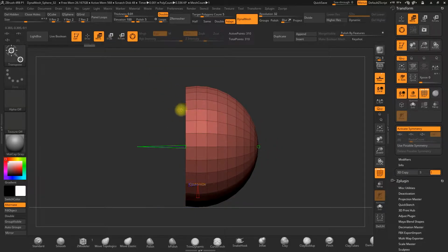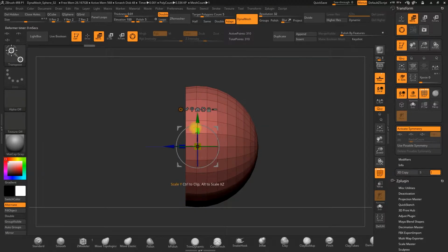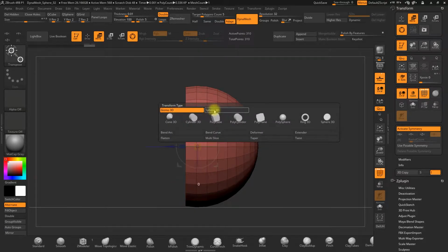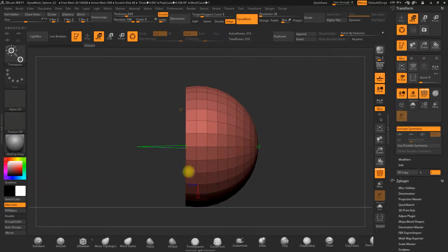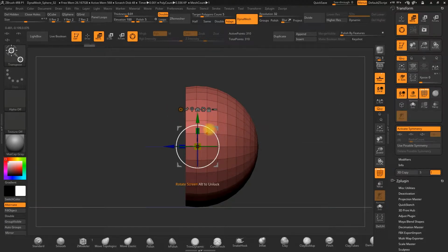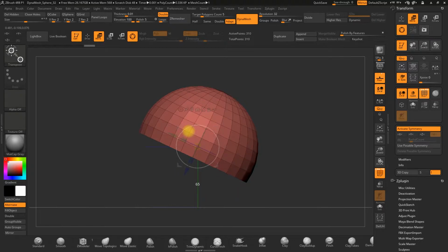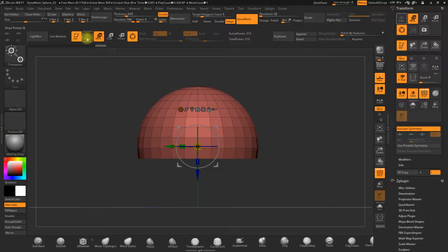Take this, click on the icon and go back to the 3D gizmo. You can go from one point to another at any time. In the gizmo, you can go back to the previous part to continue applying any modifications that you want. In this case, let's go back to the 3D gizmo. Let's rotate the sphere and with Shift, we'll turn it every 5 degrees. And we'll leave it at 90.